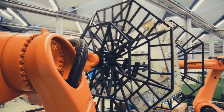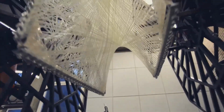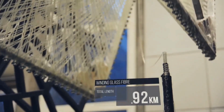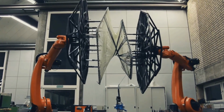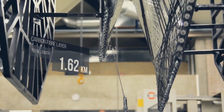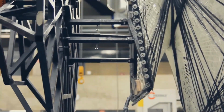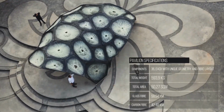You can imagine the tension that's resulting from the fibers being winded and winded is adding up and induces quite high forces into there. So then we had a fixed fiber source, and the robots would be winding around it. And they would wind a glass fiber layer first, and then a carbon fiber layer for reinforcement.